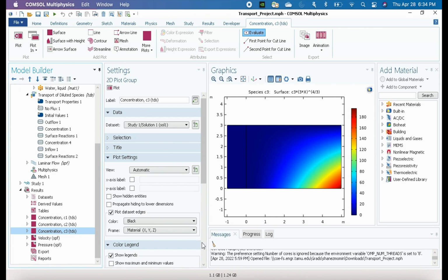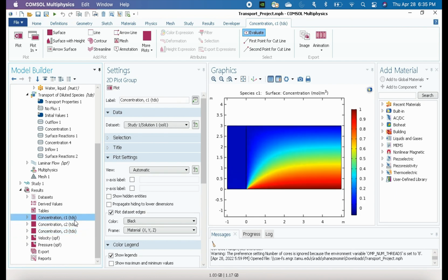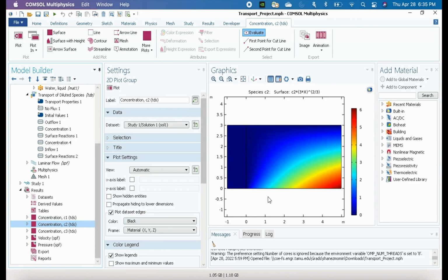As it can be seen, these profiles intuitively describe the reaction rates of the system. Primarily, as we see that the substrate is in abundance, it starts diffusing into the flowing medium right away. As the fluid flows through the channel, the reaction occurs and the intermediate is formed. After some time, the intermediate formed starts diffusing into the flowing medium. The difference in the points at which the substrate and the intermediate just start diffusing into the medium can be considered as a time representation of the reaction rates. Similarly, we see the product diffusing a little further in the x direction after the intermediate starts diffusing.